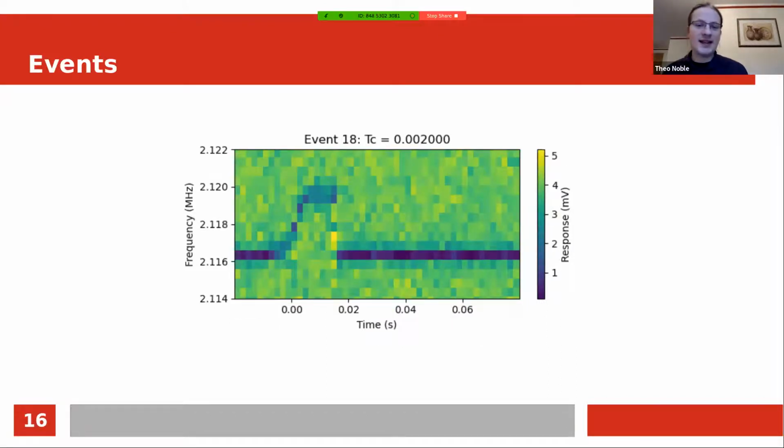You saw events like this. And you can see here that instead of just falling straight back down, in this case, we seem to have stabilized some sort of steady state at the top there, about 3 kilohertz above the usual frequency of the nanobeam. So you can see that there's this gradual rise up over the course of about 10 milliseconds or so, and it's stabilized for another 10 milliseconds before very quickly decaying back to the natural frequency of the nanobeam.